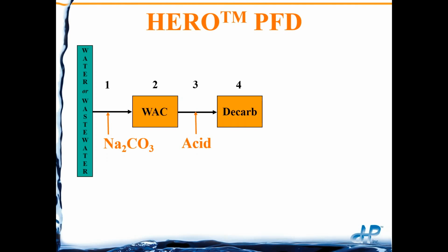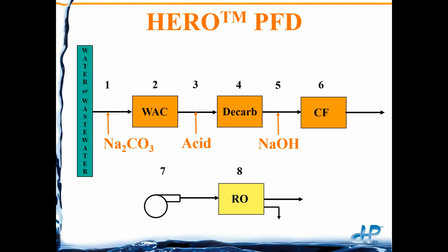If you acidify the alkalinity, it turns into CO2. And the decarbonator, which is a forced draft degasifier, or could be a membrane degasifier or vacuum, but more commonly a forced draft, is in front. Then you can go to very high pHs because you've removed the calcium carbonate scaling potential, and now you can go to very high recovery rates and high pH.